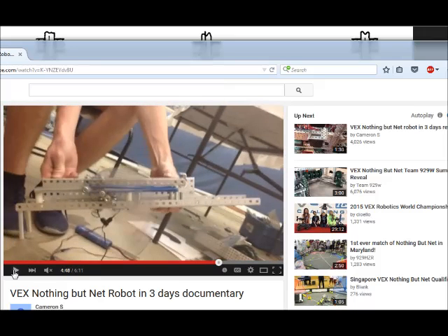So you can see that as the cam rotates, the outer edge of the spiral presses against a roller follower until it reaches the maximum diameter of the spiral, at which point it is released and the tension in the rubber bands pulls the slider forwards.